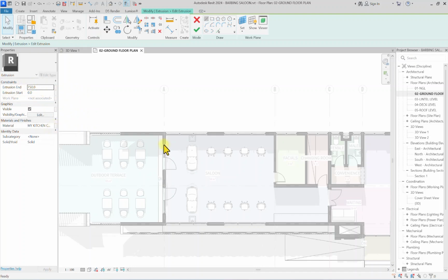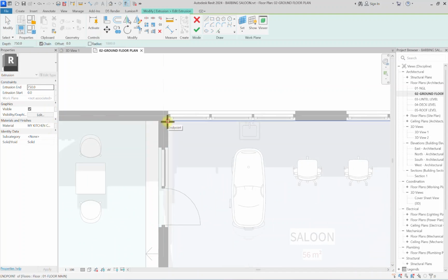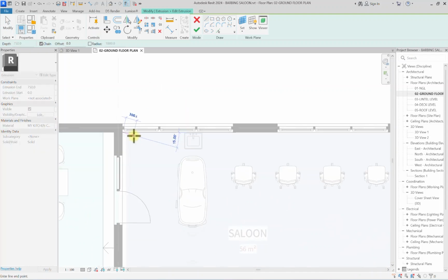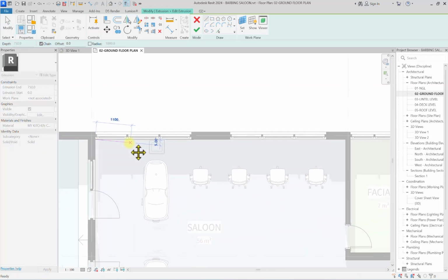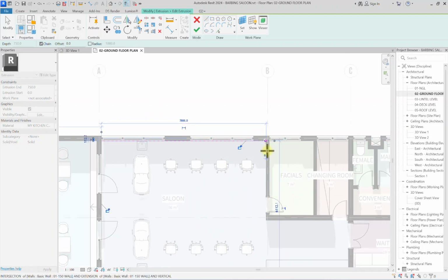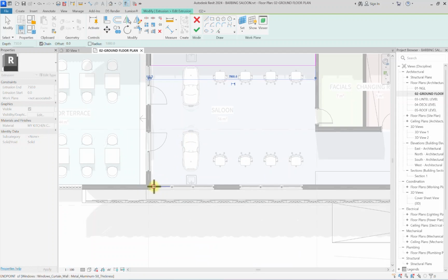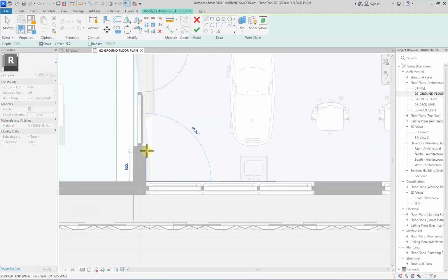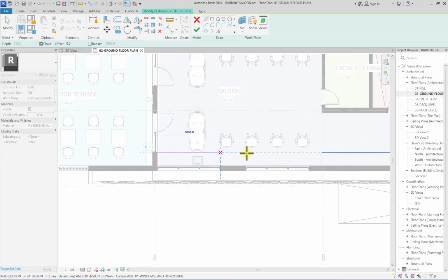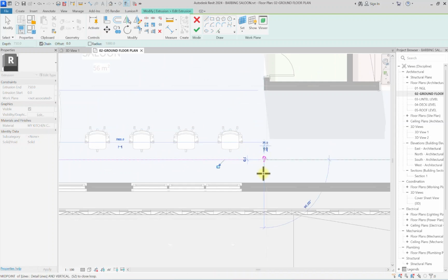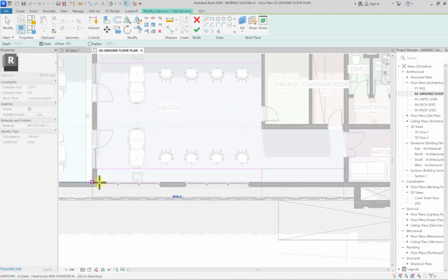Even though I'm recording this video now from the end of the project, I think I just have to do justice to this part of the video that was skipped due to some error. So I'm going to draw a line from one wall or this edge, then draw a line 600 millimeter deep, then close it here. I'm going to go to this part too and draw a line up to 600 millimeter. So this cabinet is going to be 600 millimeter deep, and draw another line here. Then I'm just going to click on finish.